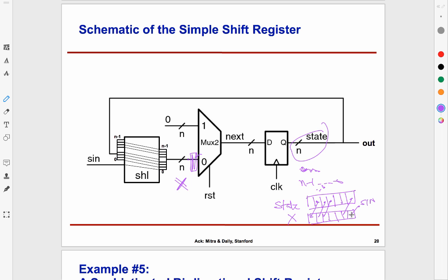Okay. This kind of shift register actually has another very important use. Your computers have serial ports. The reason they are called serial ports is because data comes over the wire serially, 1 bit at a time. But inside your computer, we want to treat it as a single n-bit variable. So what happens in the serial port is there's hardware called a UART, and one of the things it does is take bits coming in serially and assemble them into an n-bit word, which is what this is doing.